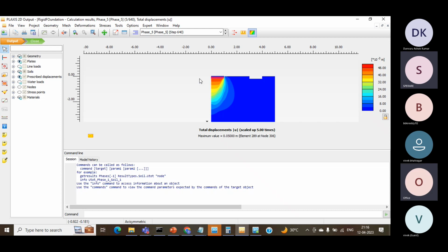Okay. Thank you very much. Is it clear now? Keep this in mind when you are doing excavation problems. If you choose a drained material behavior, what will happen? And for the same excavation process, if you choose undrained A conditions, both are possible at the site as well, and it depends upon the laboratory results that you are getting.